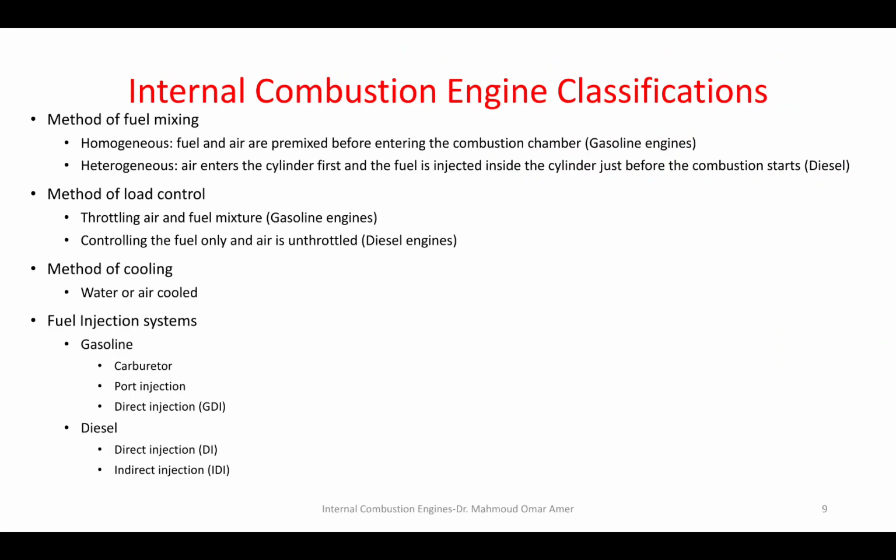If lambda equals 1, when I inject the diesel fuel, will it mix with all the air inside the cylinder? Is the mixing good between the air and fuel? No. So I have to increase the amount of air so that I enhance the chances of mixing between air and fuel. Okay? So combustion is always lean.